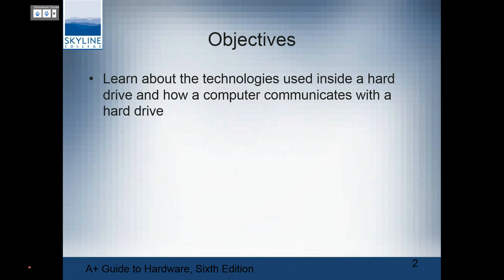A little bit different. Everything, well, they're all different. The SCSI looks like a huge PATA or EIDE or IDE. You'll hear all of those terms. And in the cable, we had the 80-pin and the 40-pin cables. The 80-pin has more grounds, and is a little bit newer.